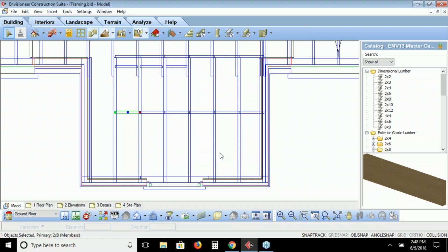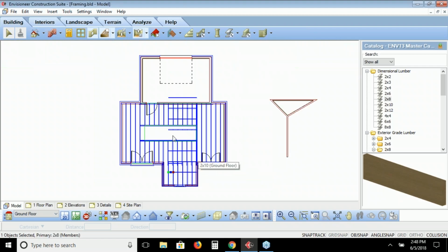So I just click OK. And then you can see how that all got copied up and across for that as well. So that would be a quick way of adding blocking, is to array it. So if it's going to be throughout the entire model on a set distance away from each other, use array. Put in one piece, array it to the rest of the pieces.